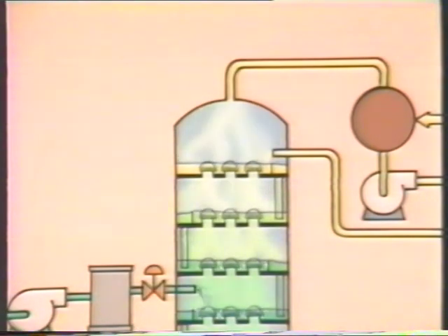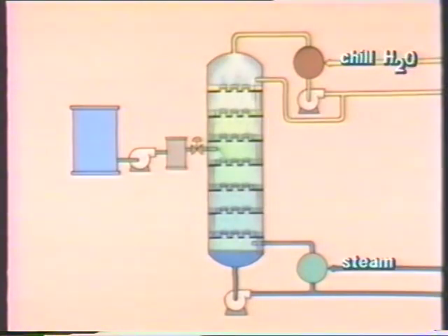As liquid collects, it rises to a predetermined level. This level is determined by a sort of dam called a weir. The liquid then flows over the weir and into tubes called downcomers. The downcomers allow the liquid to flow down to the lower tray. Each tray moving down the tower is hotter than the tray above. When the cooler liquid flows through the downcomers, it collects on the tray below and meets the hotter vapor rising up. The lighter component of the liquid is vaporized and separated from the liquid, while the heavier component builds up on the next lower tray until it overflows and continues to flow down.